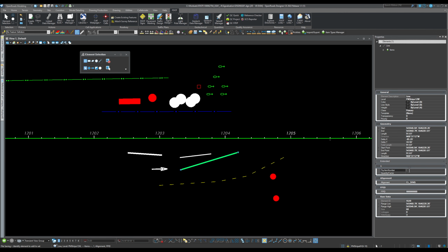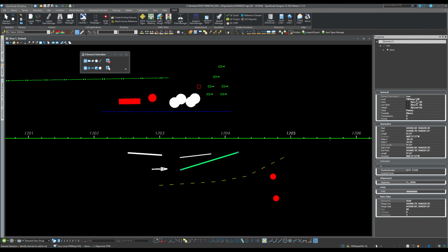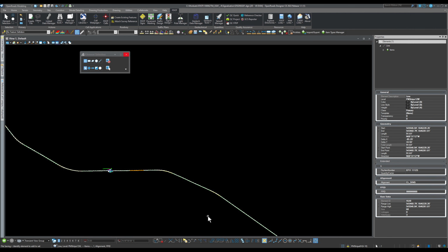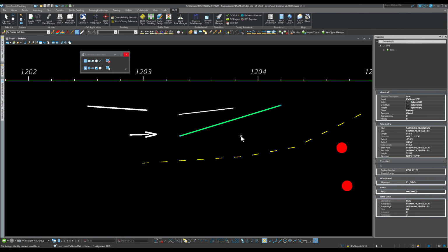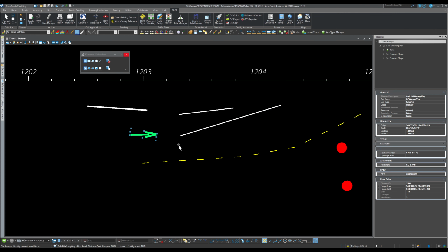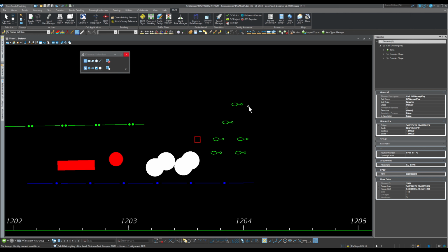One trick that I like to do when I used to do signing and pavement marking is I isolate them by type. For example, I isolate every 12 white and select all of them within the same file. Literally, I highlight everything with one click, click, click, click, add the items and be done with it. So isolating them by type is better. And for signals, you can do the same. ITS can do the same. Isolate all conduits and do it at once. Isolate all pull boxes and do it at once. Isolate all the light poles that look alike and do it at once.